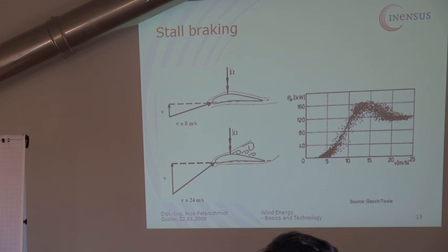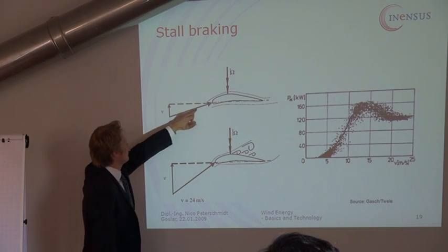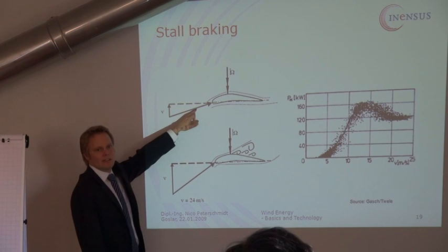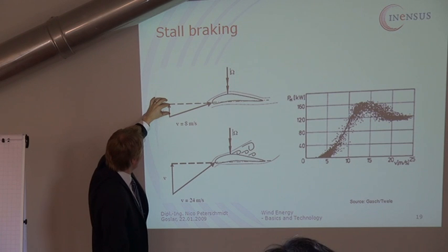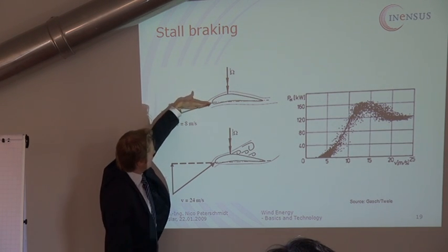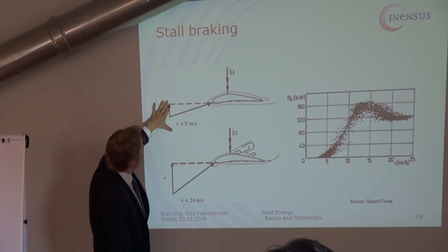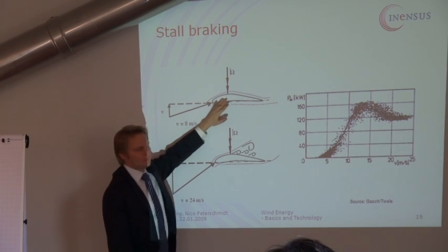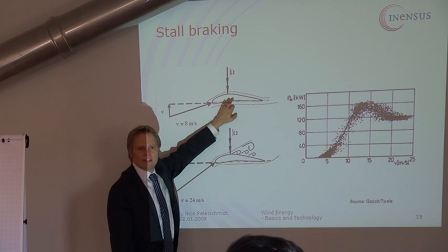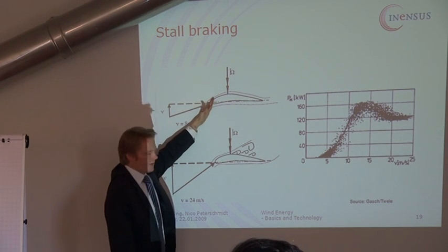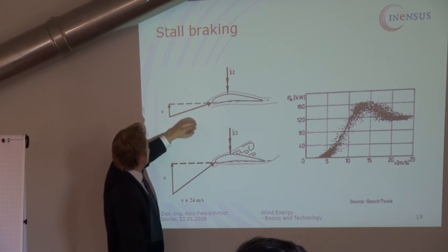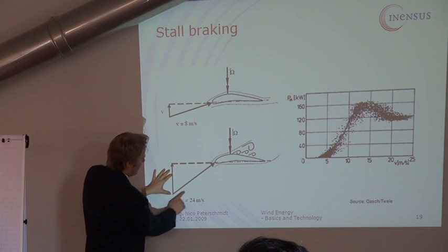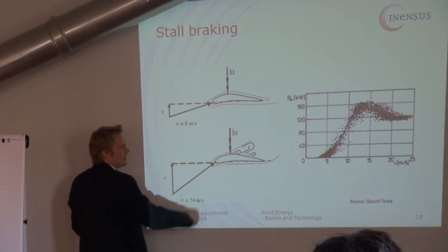All right, here we are again, that is actually what I wanted to explain to you. Now, this is the triangle, actually, the vectors. If you add up the vectors, with wind speed smaller, the angle goes like this. If wind speed is larger, and you do not turn the blade and do not change the rotational speed, the angle gets larger here. And if you make it too large, like here, you get turbulence at the end, and that is the stall effect.